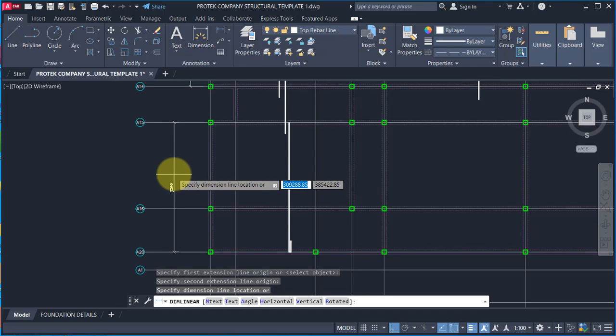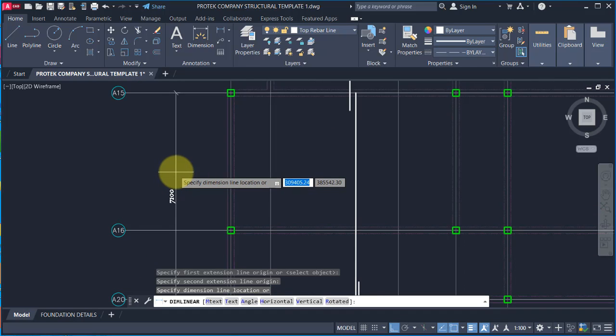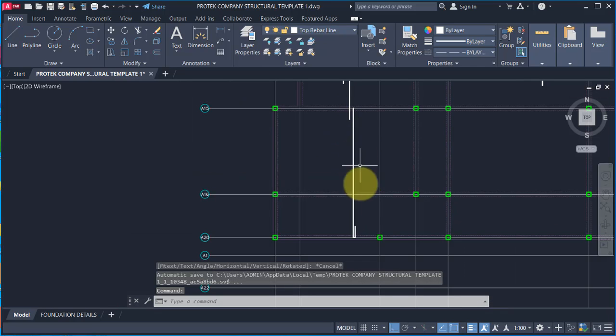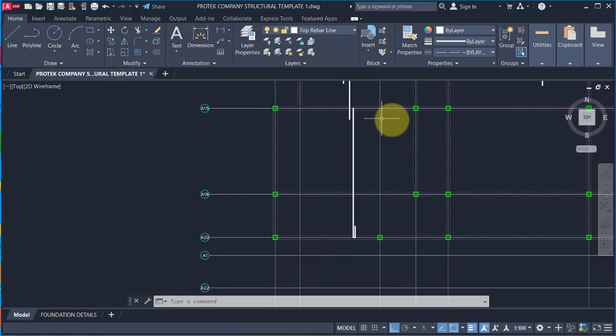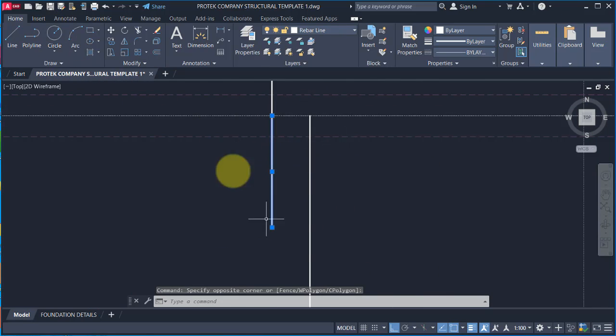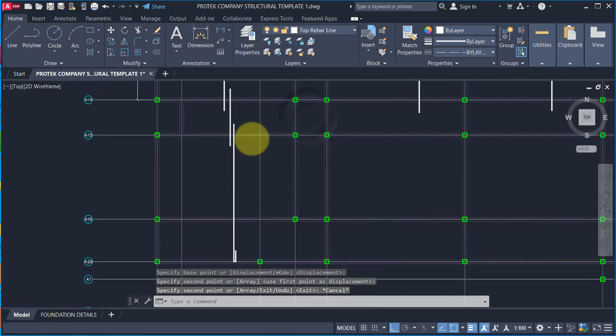So 7,100 millimeter plus the lap length of 600, you'll be having 7,700. Okay, from another 700 of the other returns. So put together it is not up to 12 meter, so you can run your reinforcement just like this. It is fine. Okay, so I want to also have 600, so I can just copy this 600 that I've drawn already. Pick copy from there, pick this point and take it here, just like this.